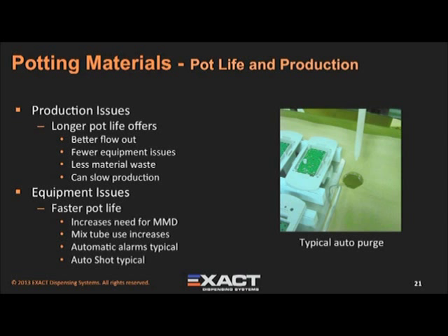There are a few other things to consider relative to pot life. As an example, longer pot life results in better flow out of the mixed material. There are fewer equipment issues and typically less material waste. But production may be slowed because the material cure takes longer.